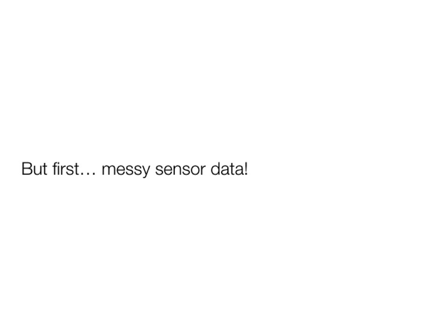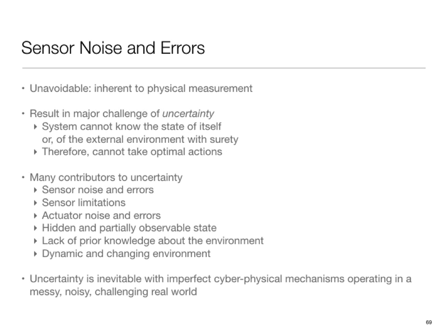Usually you would not feed them directly, and the reason simply is that sensors suffer from lots of issues, noise, calibration, things like that, and handling them upfront yields much better results subsequently. So the very first stage of a sensing pipeline is correcting these, or trying to deal with these problems.